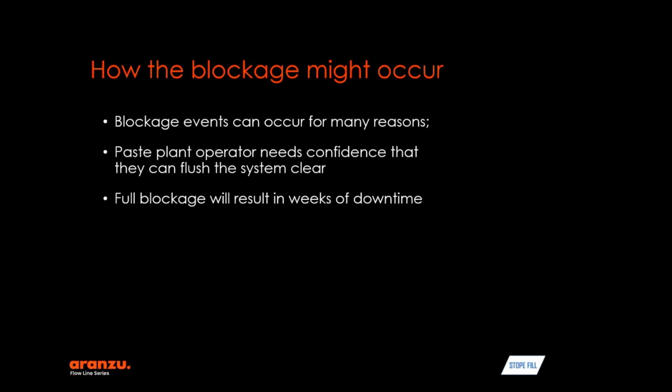So, blockage events can occur for many reasons, including rock borehole spalling failure, borehole casing wear through due to free fall abrasion, underground pipe or elbow failure, therefore with no driving pressure downstream, causing the downstream blockage, or the paste fill mixture friction loss increasing over time within the pipe, causing the system to stall.